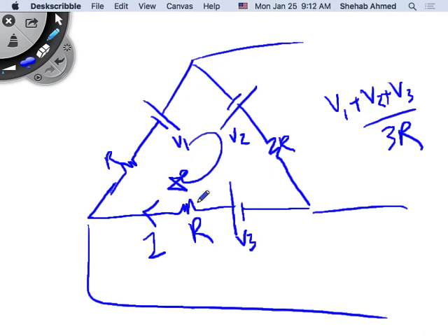You put three generators like that. Is current going to go to the load? No, because this current here is equal to this current here. The sum of current around this node is 0. This is I, and this is I. So what is this current? This is 0. So no current will come out of this generator.